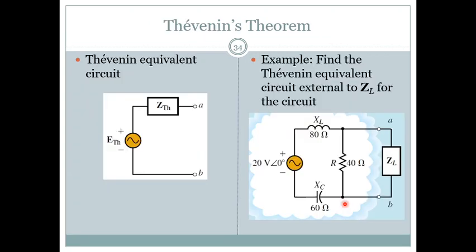So that was superposition. Thevenin's equivalent, instead of a series resistance, now we will have a series impedance. So all the things are now in the complex number domain. That is the only difference. So same procedure you follow.